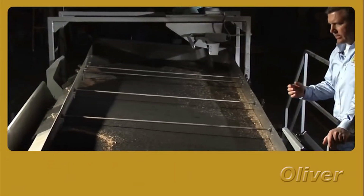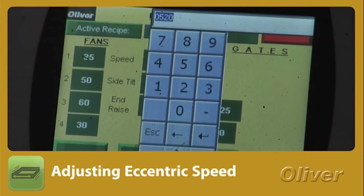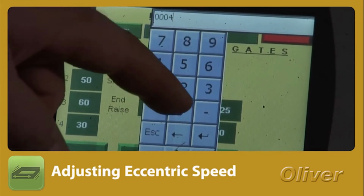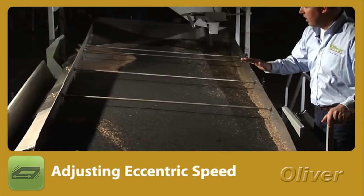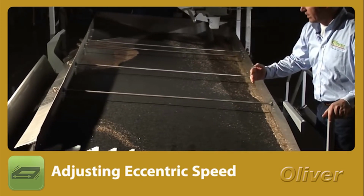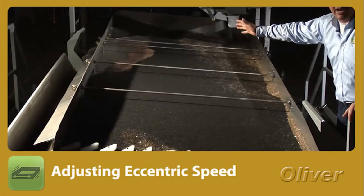The other aspect of quality separation is the control of our eccentric speed. If I slow down the eccentric speed by quite a bit, you'll see that we're not driving the heavy material up to the high end of the deck anymore. It's allowed to flow back down, and you have this problem as we see up there. That heavy contaminant is no longer consolidated against the high rail on the machine.